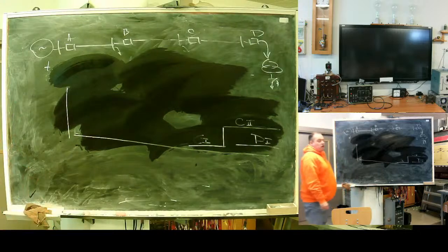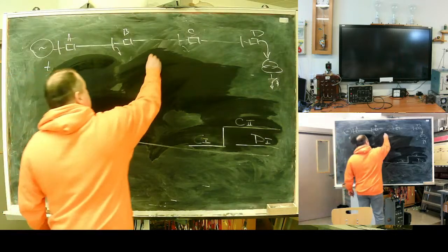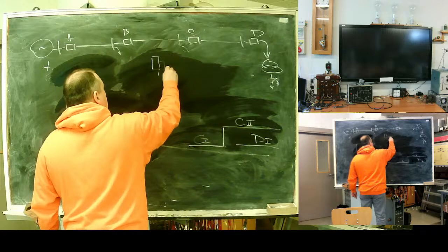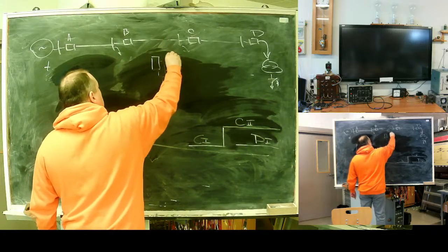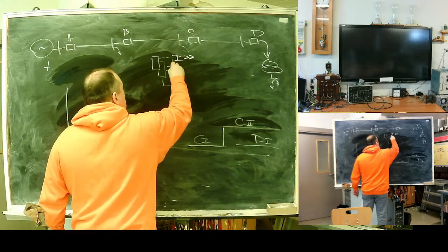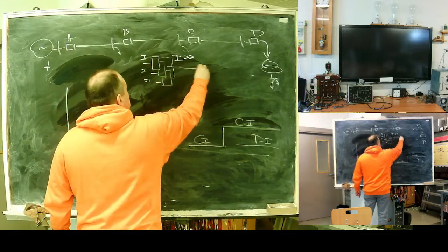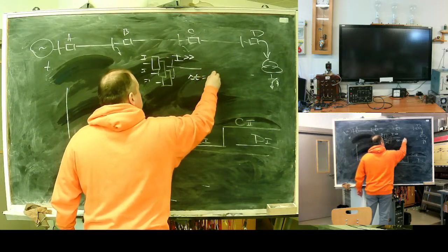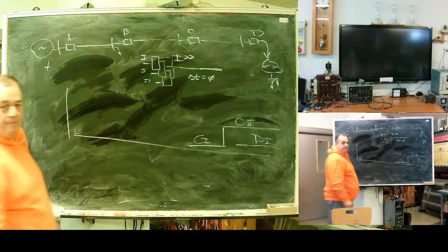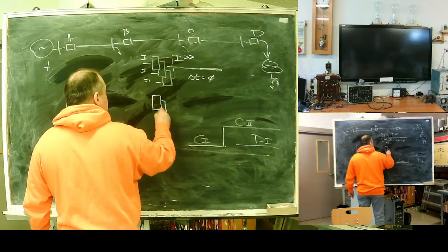I can incorporate two sets of overcurrent relays. One, what can I do? This will be very, very high current, and they will operate with zero delay. Instant protection. Plus another set.